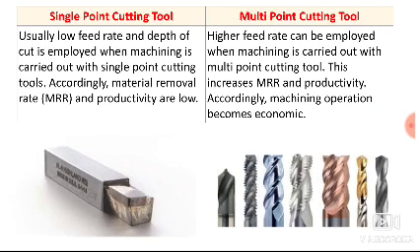Now the next reference is, usually low feed rate and depth of cut is employed when machining is carried out with single point cutting tool. Accordingly, material removal rate, that is MRR, and productivity are low. Okay, so as the cutting takes place with the help of single point only, so you have to keep